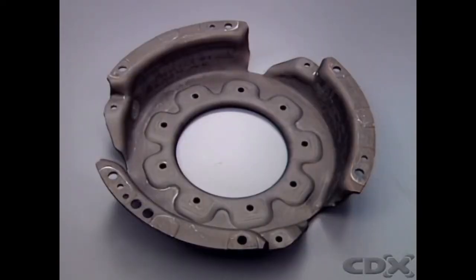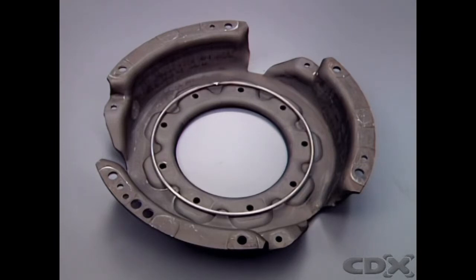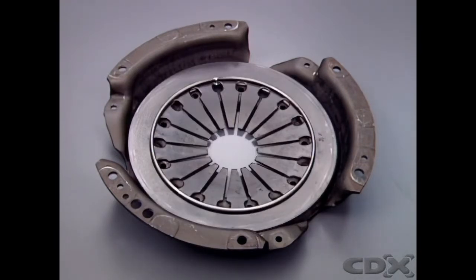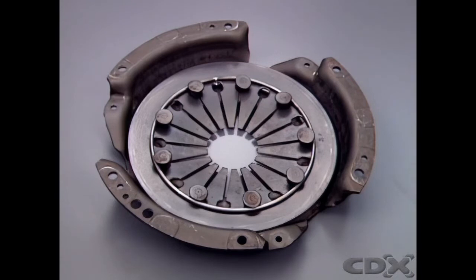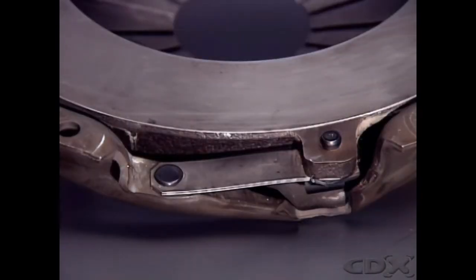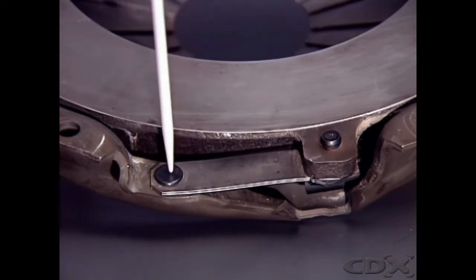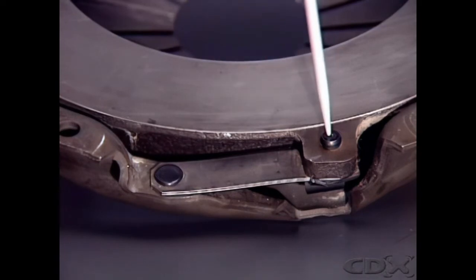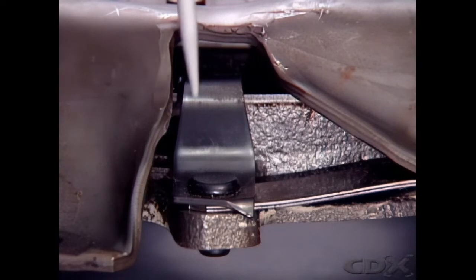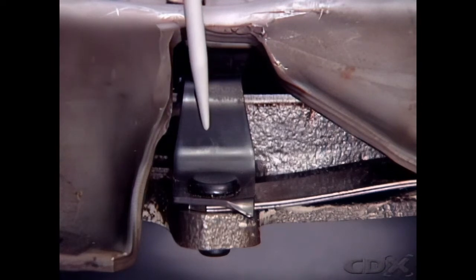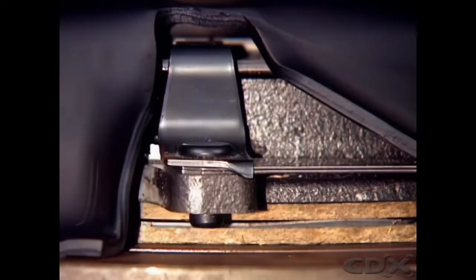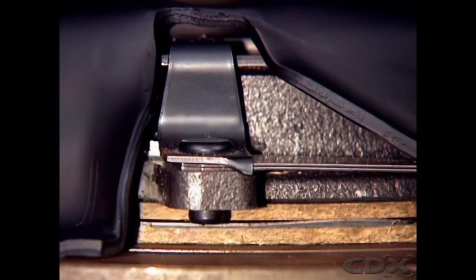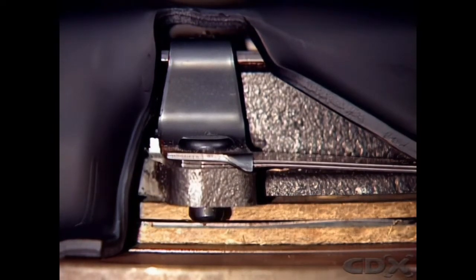This diaphragm is located inside the clutch cover on two fulcrum rings, held by a number of rivets passing through the diaphragm. The pressure plate is connected to the cover by the spring steel drive straps, riveted to the cover at one end and to projecting lugs on the plate at the other. Retraction clips hold the pressure plate in contact with the outer edge of the diaphragm. During clutch operation, they move the plate away from the flywheel.